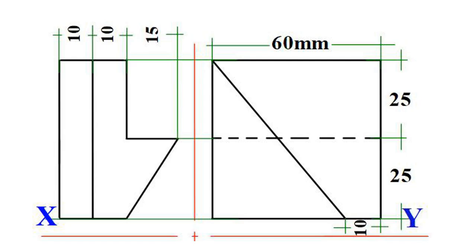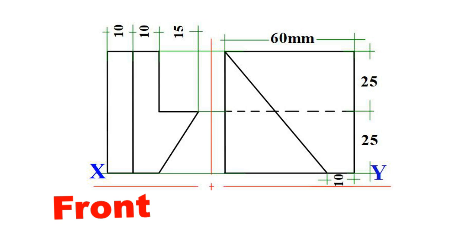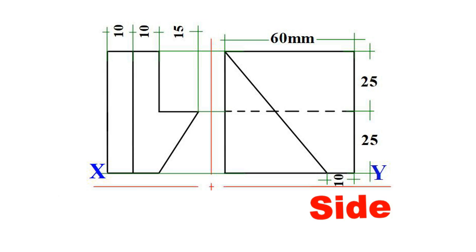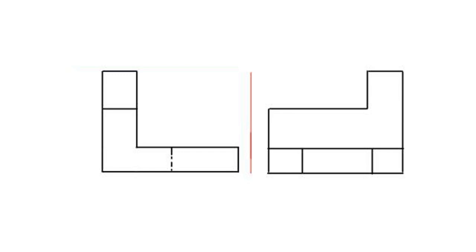We can construct an isometric view from orthographic views. If you have two orthographic views like the front and side views, we will discuss this example later, but for now, let's start with a simple example and make it simple. You can construct an isometric view. Here's how. 1. Start by analyzing the orthographic views to understand the object's dimensions and shape.